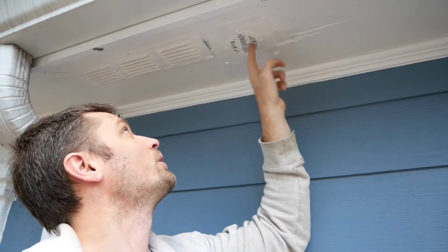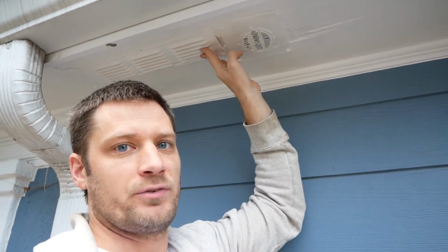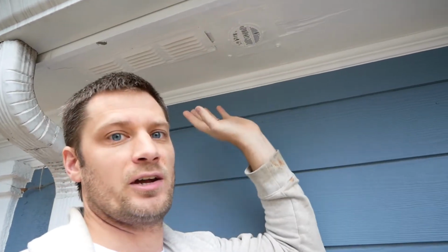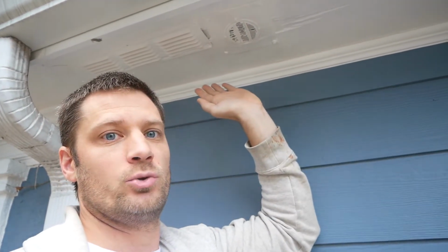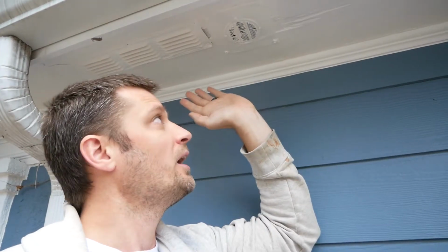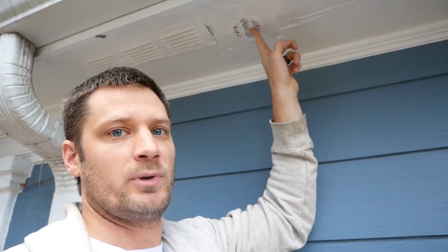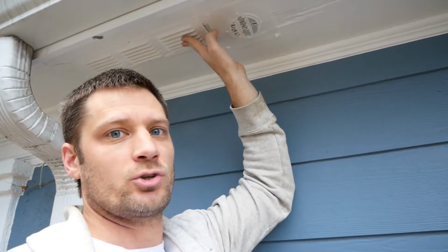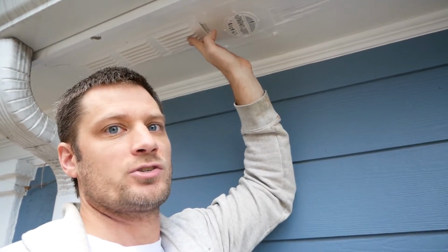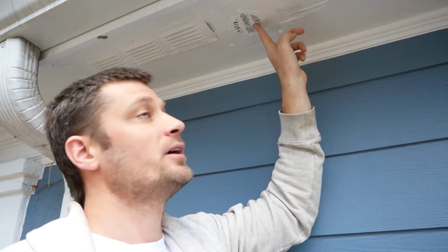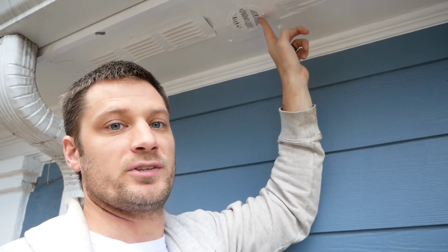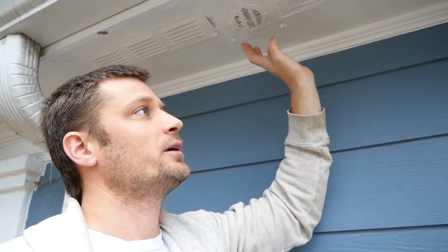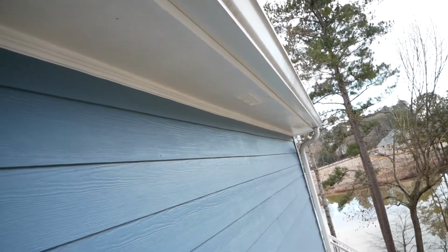But a major problem I do see here is that this is right next to this soffit vent. So this soffit vent is to bring air inside the house to help cool it down next to the roof. And the fact that we're pushing humid air out and it can come right back in could create mold. So we definitely don't want that to happen. So what I'm going to do is replace this vent here with a dampered vent, and I'm going to locate it on the soffit in between this soffit vent and the soffit vent that's located down there.